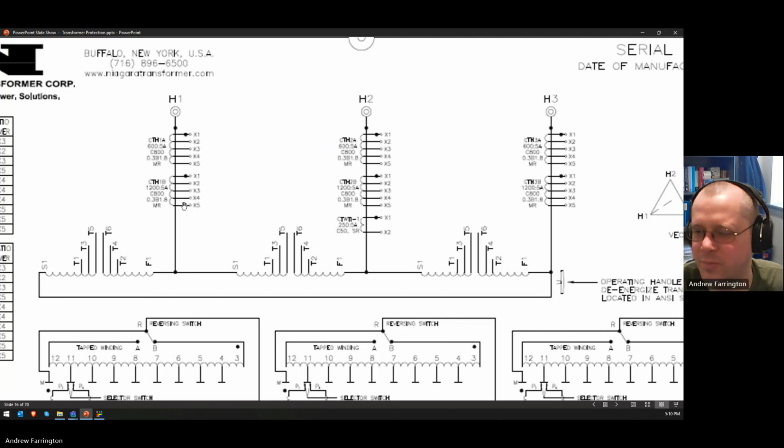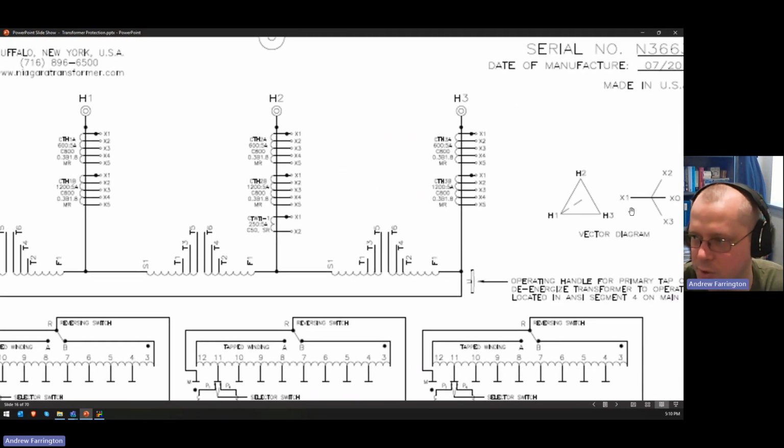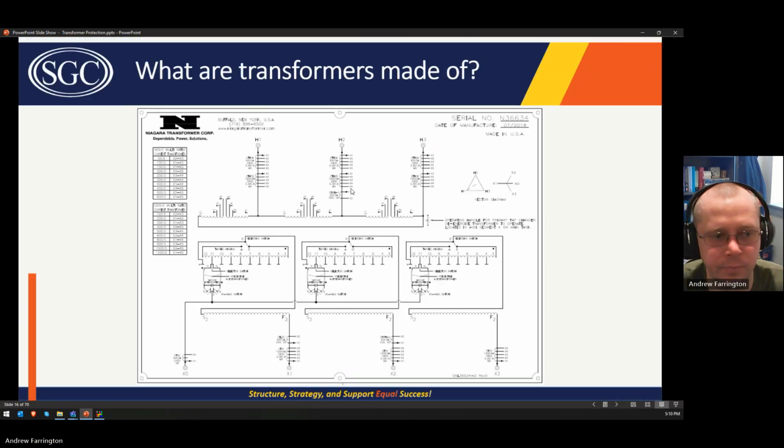I don't know if I'm explaining that quite well, but here's the polarity, right? F1 to S1 is this, so this is the polarity side. So here's the polarity side of H2. So the non-polarity side of H2 is here. So this is DAB. DAB is a DY1 transformer. So the vector diagram should look like that.